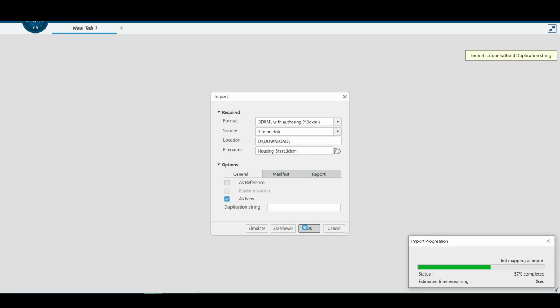Here we will create the different types of view. This can be done to extract the 2D drawing using the view from 3D functionality from the drafting app. This drawing will automatically have all the annotation created using the 3D tolerancing and annotations.